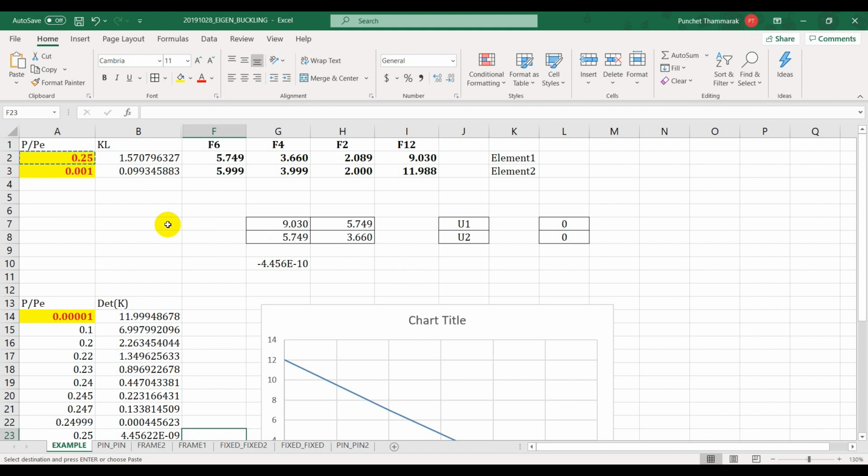of the PE, which is equal to pi square EI divided by 4L square. The K for the column with the fixed base is equal to 2, right? So the KL term as the denominator, when it is squared, you get the 1/4 factor, which is 0.25. Okay, you can get it. This is by using the stability function.